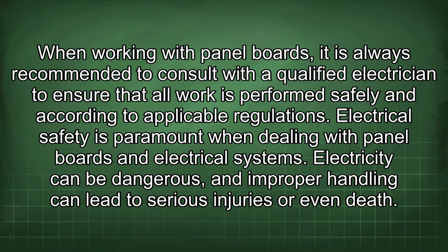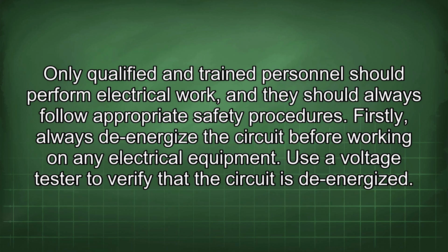Electrical safety is paramount when dealing with panel boards and electrical systems. Electricity can be dangerous, and improper handling can lead to serious injuries or even death. Only qualified and trained personnel should perform electrical work, and they should always follow appropriate safety procedures. Firstly, always de-energize the circuit before working on any electrical equipment. Use a voltage tester to verify that the circuit is de-energized.